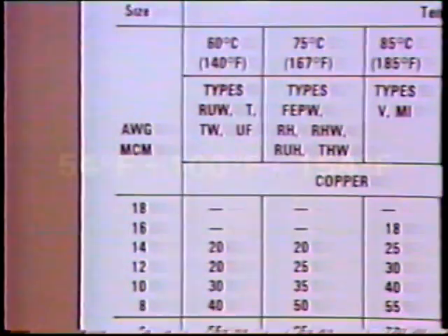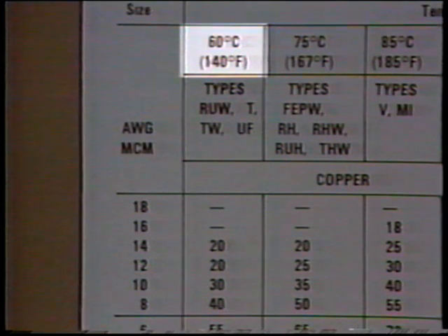Let's find out what its maximum operating temperature would be. We add the 54 degrees Fahrenheit internal temperature rise to the actual ambient of 100 degrees Fahrenheit, and we get 154 degrees Fahrenheit. Well, that exceeds the limit for this conductor. It can't carry 40 amps safely at 154 degrees Fahrenheit. What we need to do here is to derate the conductor. In other words, we have to determine how many amps it can safely carry at an ambient temperature of 100 degrees Fahrenheit. When you derate its ampacity, you're actually reducing its current carrying ability to match the needs of the environment.